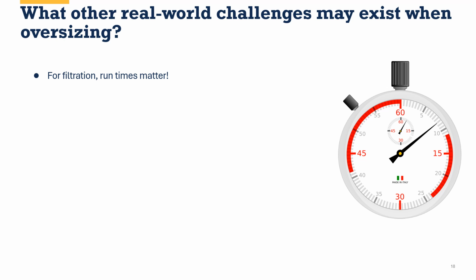So around 55 minutes per hour would be ideal, as long as it's not at full speed to do that. If we can be running like that, and most of the time is half speed, half power, with some ramping up, that's fine for 55. Then during the rest of the year, what we call our shoulder seasons, or during the warmest part of a cold day or the coolest part of a warm day, if it dips down to 30 minutes, that's probably just fine. What we want to avoid are under 30-minute run times. That's where we get our problems.